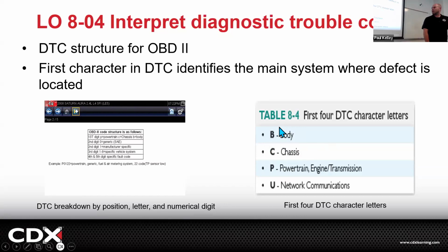However, later they were sort of like, you know what? This OBD II system's kind of good. If the manufacturer wants to, they can put a whole OBD system on your car's body, monitor all your lights, your switches, your windows. And now they do. For 20 years, cars have had body control modules and ABS control modules, and they all work the same. They all have monitors, tests, set codes, freeze frame, and live data, but we mostly focus on powertrain.